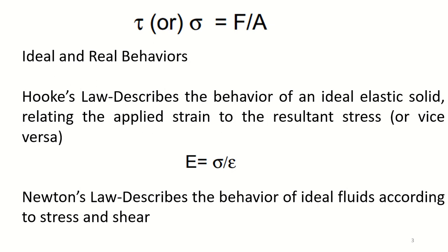Newton's law describes the behavior of ideal fluids according to the stress and shear. The proportionality factor is viscosity. Ideal viscous fluids are linear in terms of shear rate, not shear thinning.